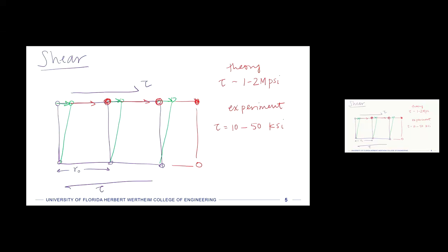And so they had to go back and think about this again, right? Because they said, okay, if all of a sudden I'm pushing on a material and then it yields and I can see it sort of at the micro scale, to me it looks like it happens instantaneously, but clearly it can't be, right? Because we would need to have a much higher shear stress to have all those happen simultaneously, which we don't have to have. And so there must be something more progressive that is slowly moving through the material, slowly, but faster than we can see. And so that's when dislocation theory began, and that was in the 1930s.